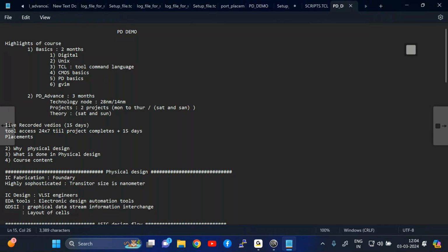When we purchase digital macros like memories, they will first write Verilog code and do all the steps we have done. They'll create the GDS and LEF files and give them to us. Inside that there can be cells, but when it reaches us, we cannot see what is present inside. We can only understand that it is a layout. That's it.